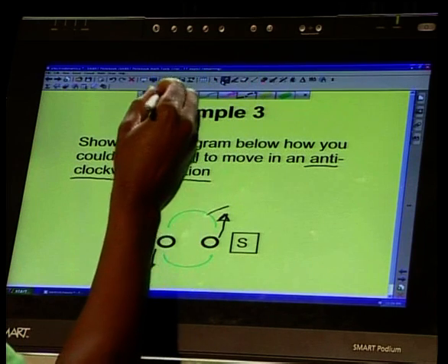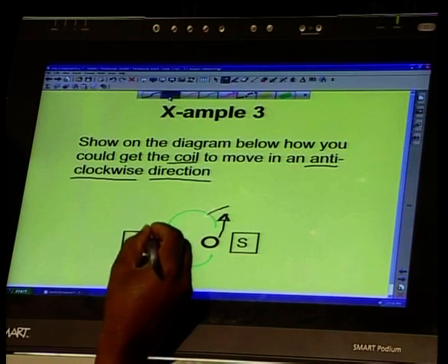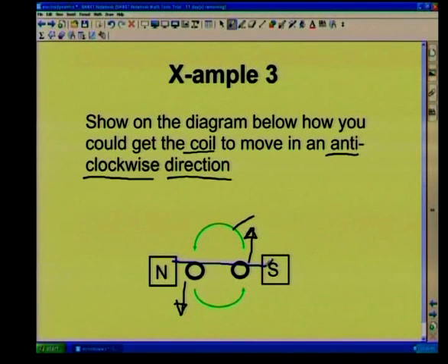But what we know from the magnets here is that the direction of the magnetic field is from left to right, north to south. So if we want the force there to be pushing downwards, let's just look at the left-hand rule. There is the direction of the magnetic field. If the current comes out of the page, it will be pushed upwards.